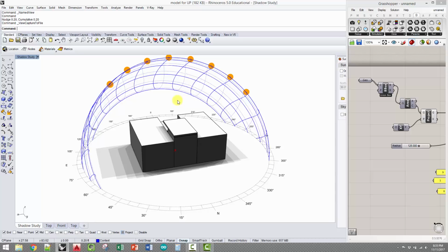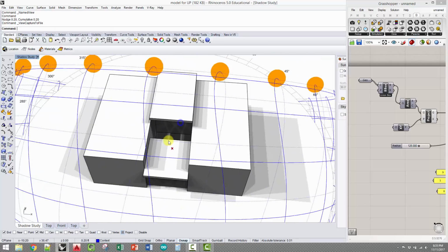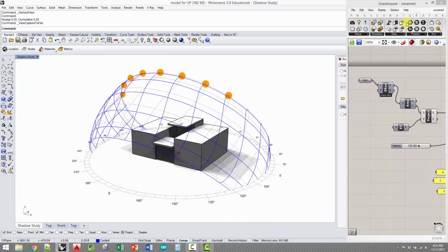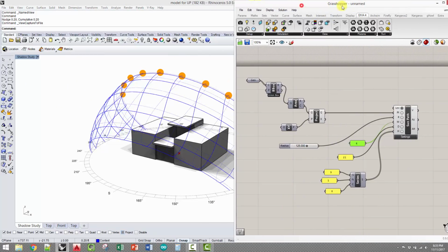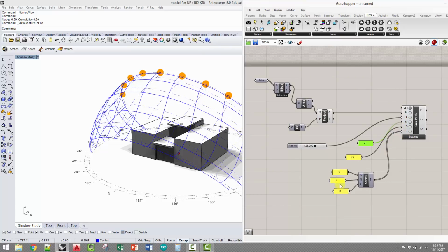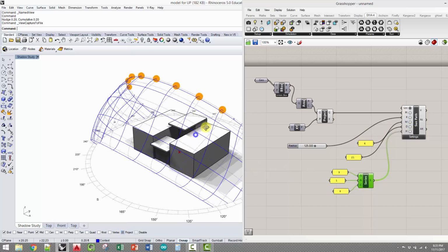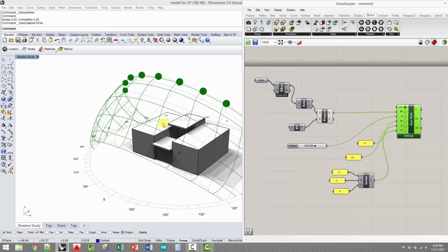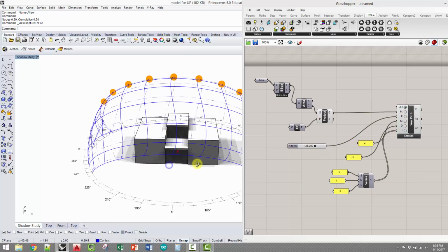So that's a way to look at the study. And what you're looking for is where your building is casting shadows, where the neighboring buildings are casting shadows. You may be more interested in things like your courtyard, if you have any, or any kind of interstitial space or transition. But just making sure that you're not getting too much shade or too much glare in that space, and that's the advantage of this light study here. If you wanted to do a series for the month or for the day, you absolutely could. You could actually graph the whole year at the same time if you wanted to. But for this assignment, we're looking at the 8 hours, from 9 o'clock to about 4 o'clock, over the course of the equinoxes and the solstices. But again, it's your call. That's what this component does with DIVA. It makes this really great visualization, and I think it's pretty useful.